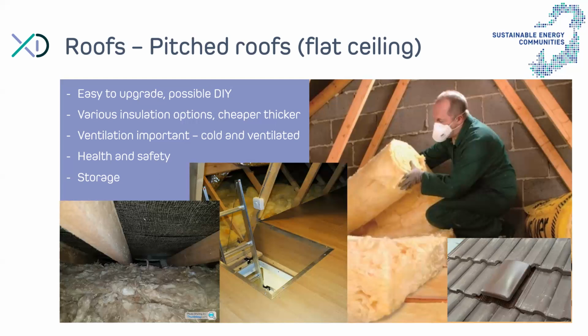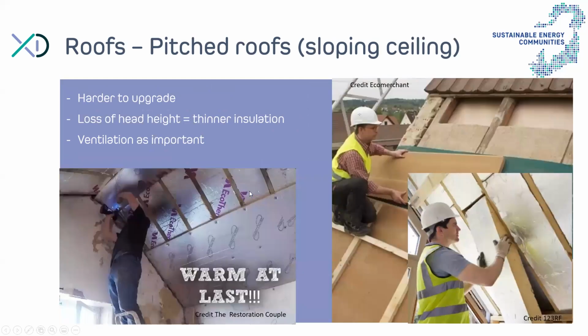Finally, it's worth mentioning cold water tanks in the attic, if there are some, and they need to be protected, you need to prevent frost from happening there. So it's always useful to maybe put a minimal amount of insulation below the tank, but then wrap the tank itself so that it's protected from the frost, the very cold conditions that might happen in the attic. So I think that covers all the different aspects of, let's say, typical attic insulation.